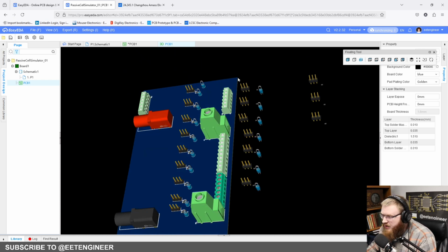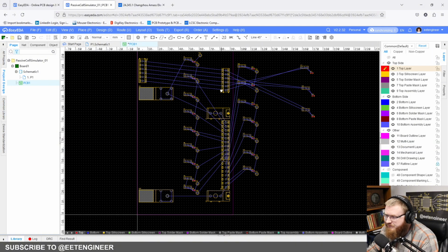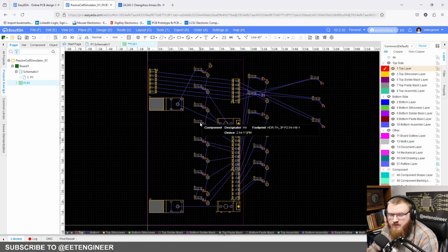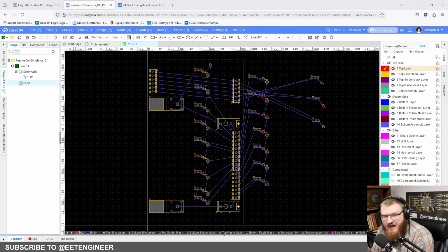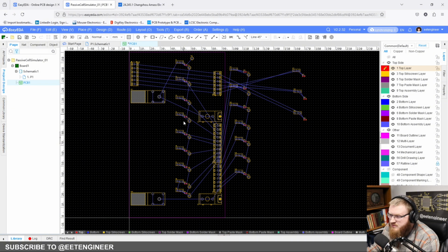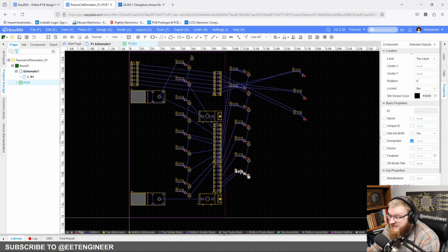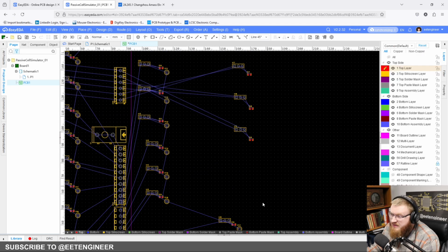So next comes the hard part, which is getting all of these cell connections together and getting them nested. So I'm going to show you what I created to make this a whole lot simpler. These are stacked in here the way they are in the schematic. So here's cell 16 all the way, and then back up, and then down through cell 0 here. Everything is connected the way it was in the schematic, and then here are your thermistor ones.